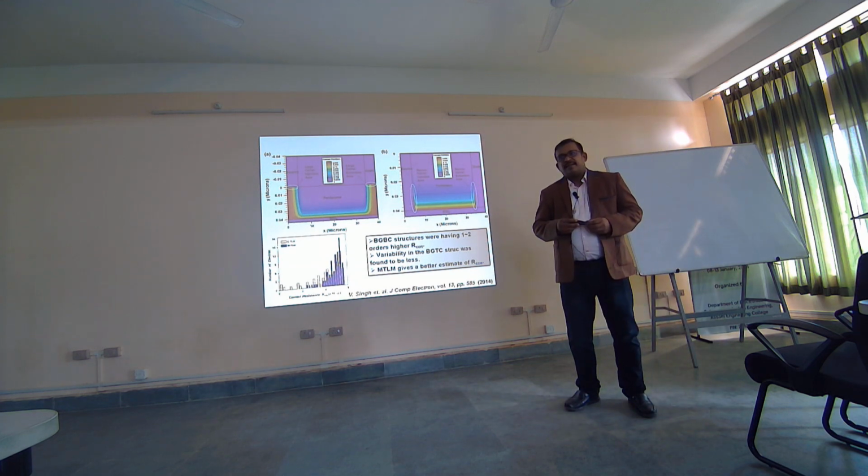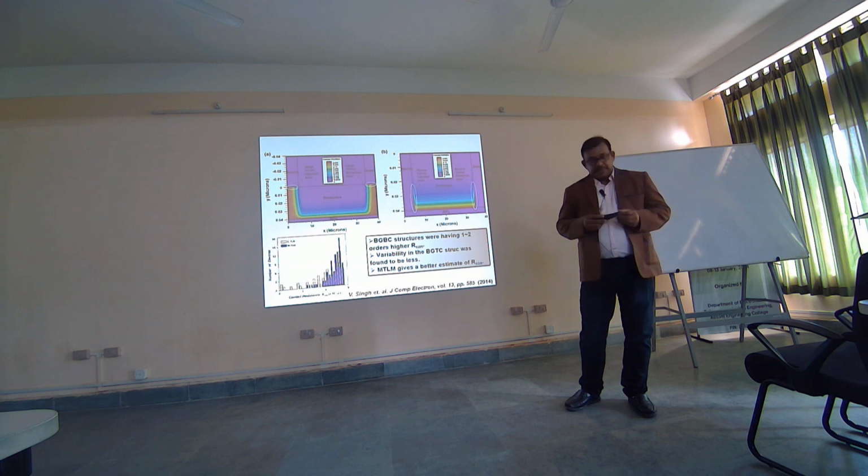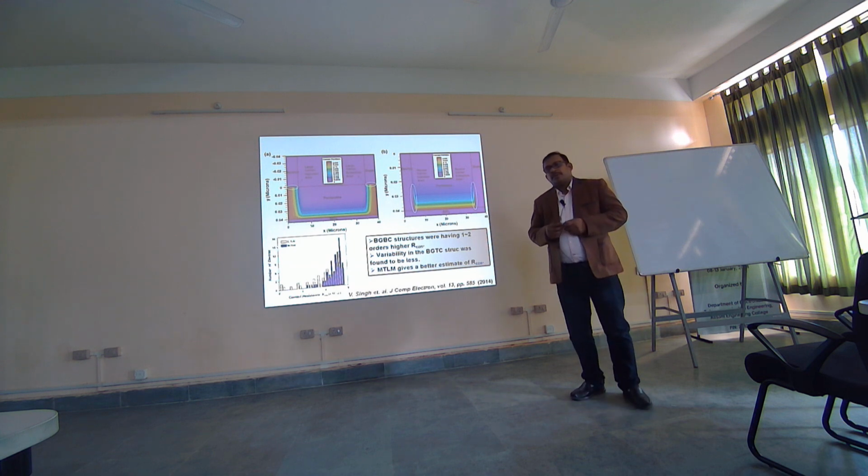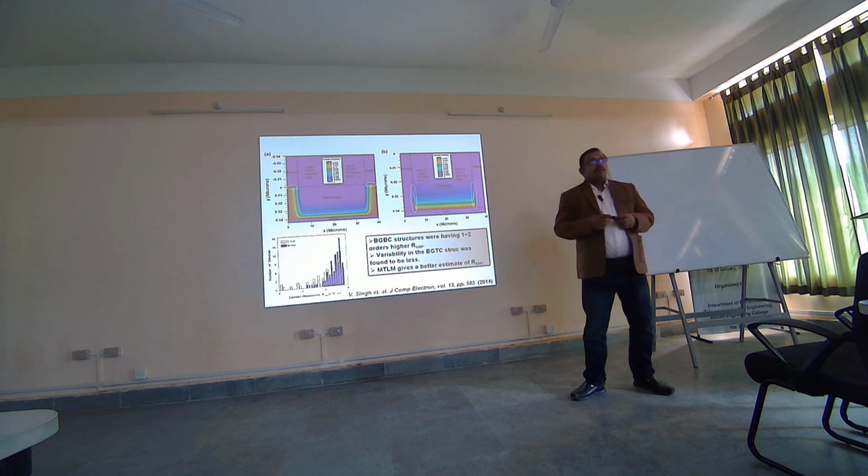If I can use your expertise, sir, my question is from the fabrication point of view. When we try to deposit this sol-gel on a substrate, I came across three issues: cracks in the thin film, viscosity, and adhesion with the substrate. Sir, can you suggest any solution for this? Any reagents that we can use?